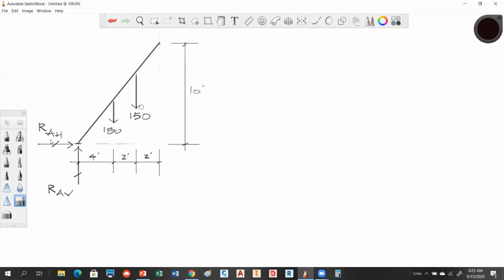So perfect. What you told me is completely correct, because this wall is here, this guy's free to move up and down along it, but it can't move this way. So what we're going to do is indicate a reaction, and you said you want it to go to the right? Okay, so we're going to go to the right. Okay, so that would be reaction, we'll just call that B.